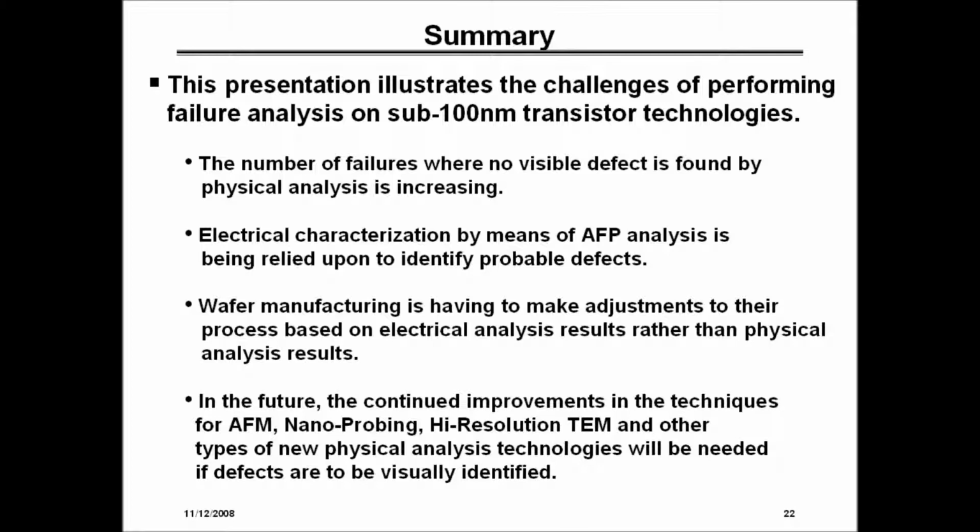It's gotten to the point where they can localize through microprobing a number of circuits, maybe a number of muxes, but they only get it down to the point where they can see the signal going in and coming out, and then there may be maybe a dozen, 2 dozen transistors that may be the problem. And through partial delayering of the sample and accessing the metal lines at higher levels, we can toggle the input and then see what happens on the output.